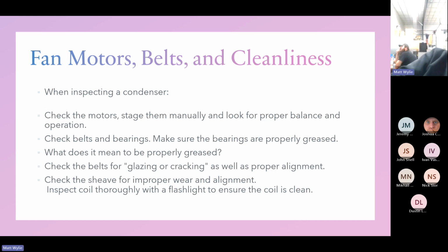So check the sheaves or pulleys. Should they be even? Should they have grooves on them? There shouldn't be any. They should be nice and smooth, with no grooves or bumps.